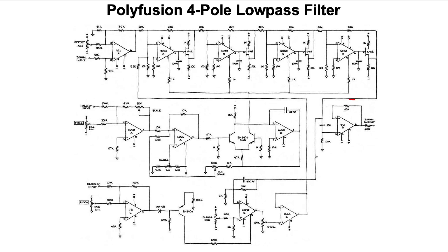So we have the signal coming in, going into the input of this OTA. Here's that 2K, 10K kind of divide down ladder. An interesting thing about this is this does not actually divide down the voltage very much going in. That's dividing it by, let's see, it'll be 2K over 12K, so 1/6. Usually we saw a much heavier amount of attenuation in the front.